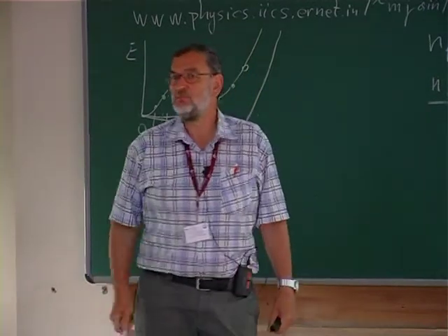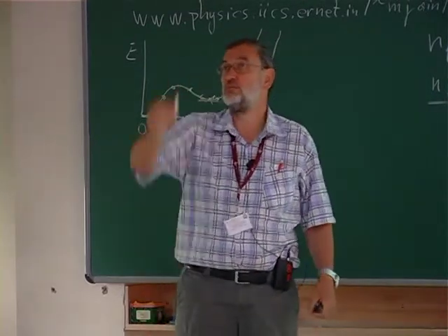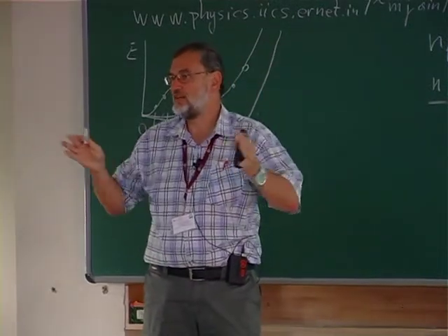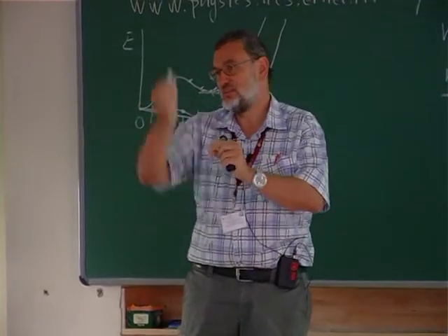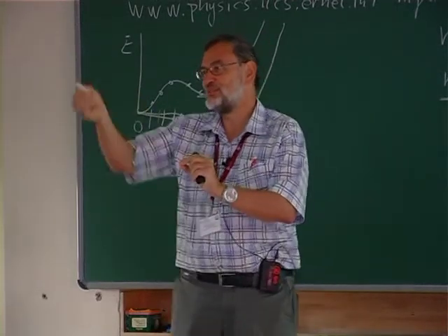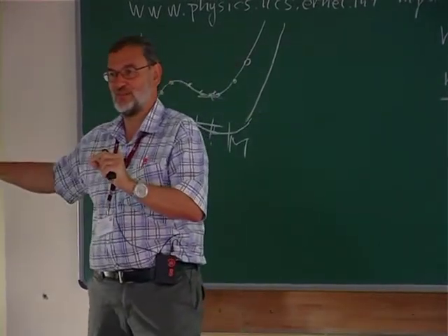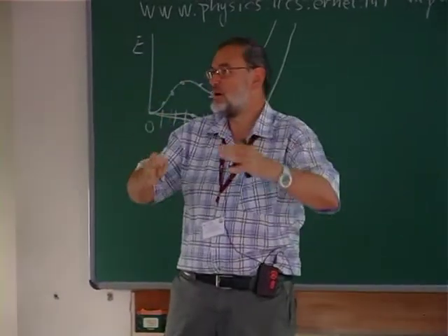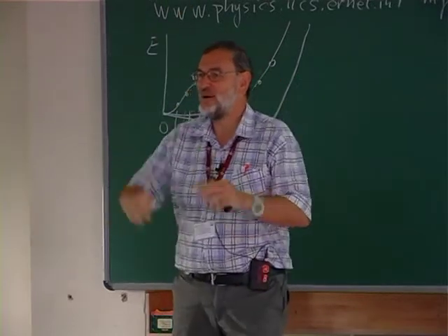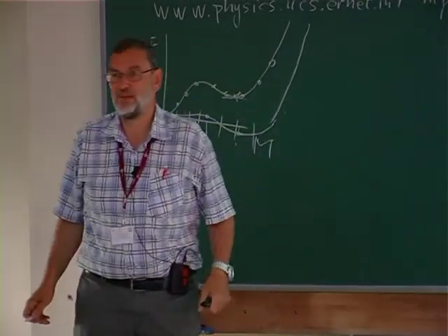And people have really put a material, for instance, a nickel iron alloy in the right concentration, put a wire on that, and this alloy has no thermal expansion. And with this alloy, with this wire connected at the top of the Eiffel Tower, they measured with some device how much the change of the Eiffel Tower with temperature was. Okay? You had the Eiffel Tower, normal steel, which changes its length with temperature. The iron-nickel alloy stays constant with temperature, and then you see the difference between these two lengths.